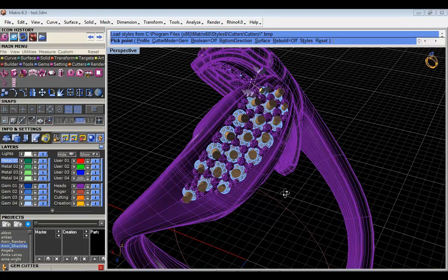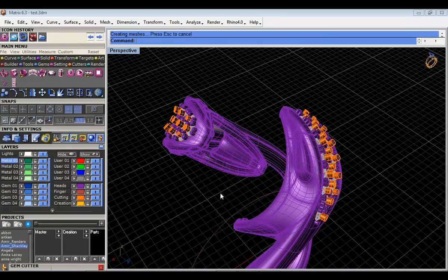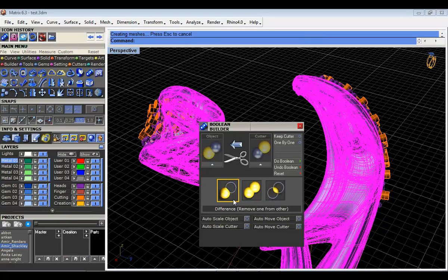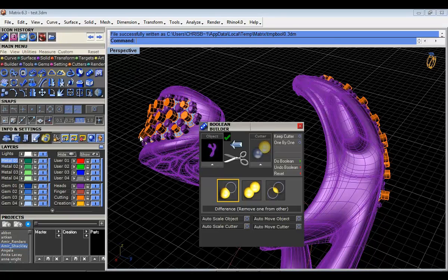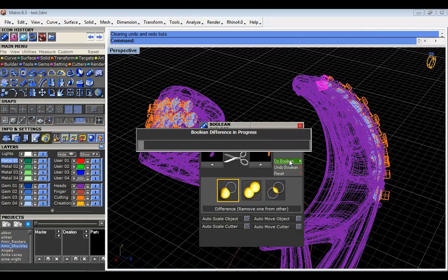There's one question just at the very start of the webinar about getting accuracy with T-splines, and I guess I can take a stab at that, and I'd be interested to hear what you actually do, Chris. So as far as accuracy, one nice thing about T-splines is you can start with NURBS, and as long as they're not trimmed, you can start with curves, and so you can get a T-spline to come out of a specific curve. You can also use the T-splines match command to match the border edge of a T-spline up to any curve or poly surface. So those are probably the two ways that I think of accuracy.